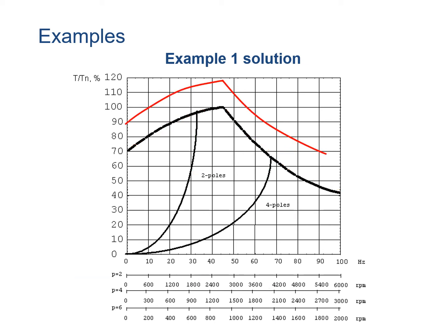Okay, in both cases, what is important is that our system curve should be above these points, above the generic system curve. See, there should be some buffer between, ideally as small as possible, maybe 2%, because the pumps don't have any overloads, so you can dimension it very close to what you really need. But if you have a 5–10% buffer above, that would be good dimensioning, no problem.